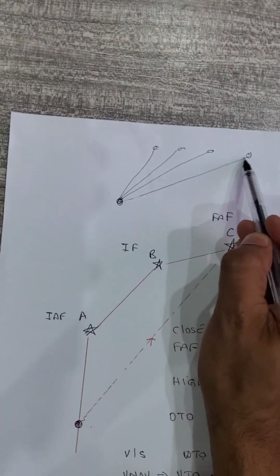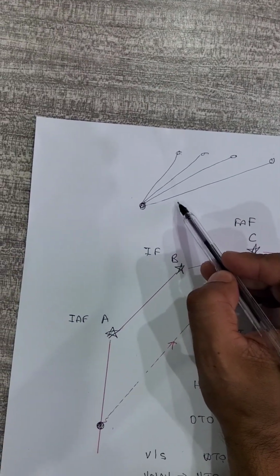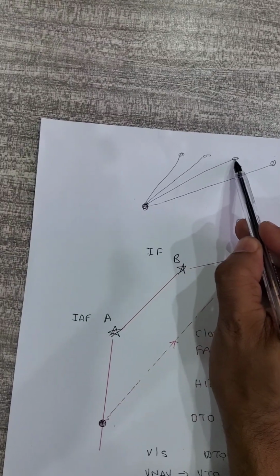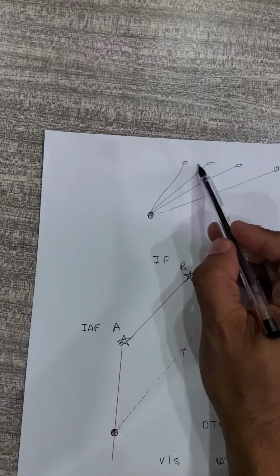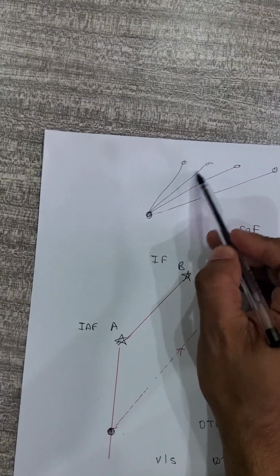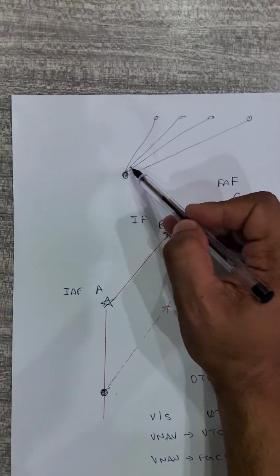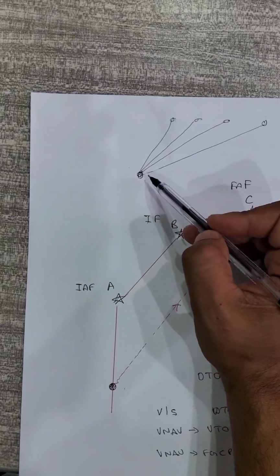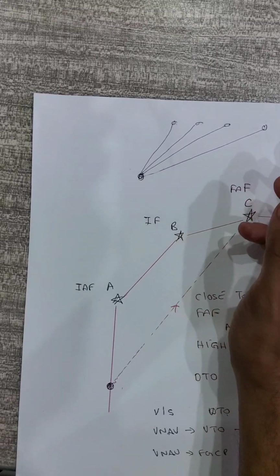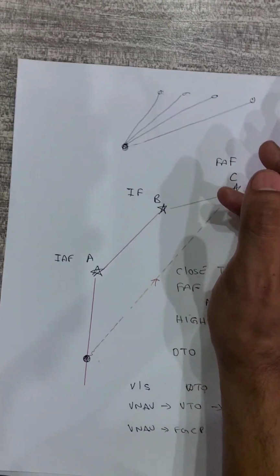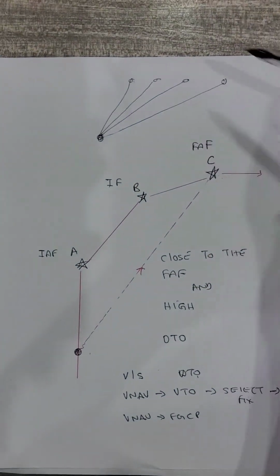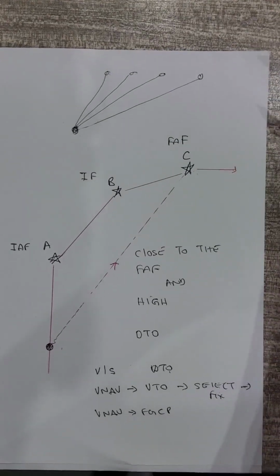From here the FMS will be able to calculate at a certain rate of descent. As you get a bit closer, it will be able to calculate, but then there'll come a point where it will be like, now this is just ridiculous. Okay, the vertical speed will be so high, maybe 3,000 feet per minute. I mean, you don't want to do that. You don't want to actually try and do such maneuvers in commercial flying.